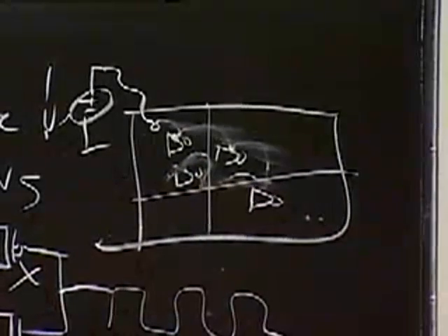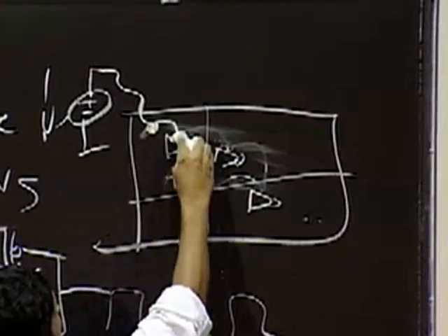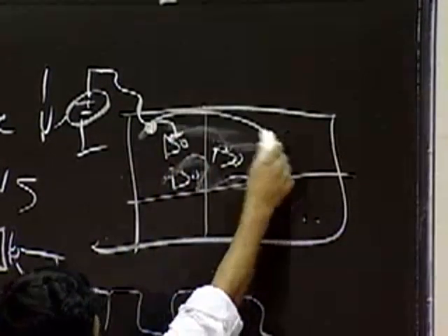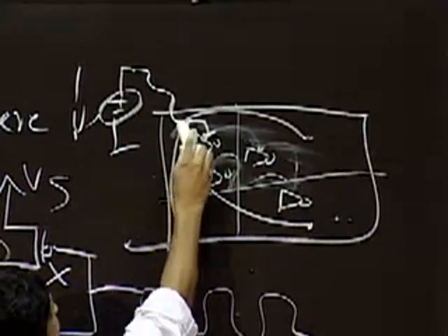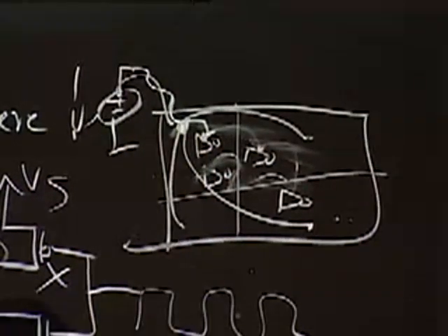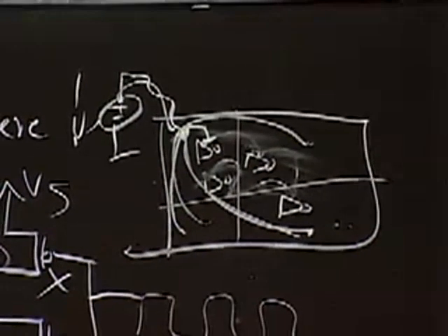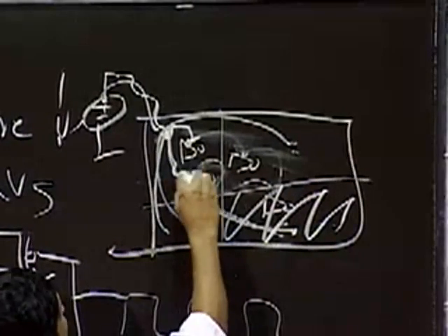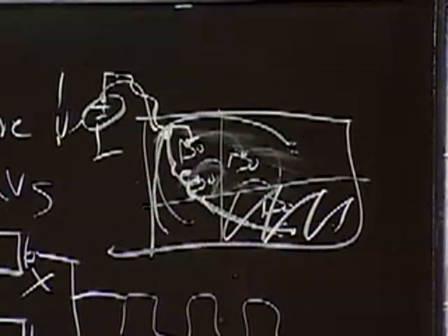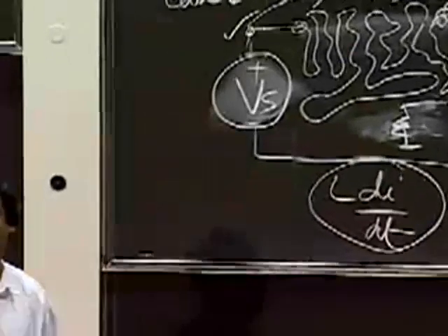In our case, we had 16 quadrants. And then from this point, you take one wire that goes to this quadrant, one wire that comes here, one here, and one here. That way you're getting the power supply very close to the source, and you have different connections going to each quadrant, so that switching in this quadrant does not affect this one because of the inductance of this lead here. And if you hadn't taken 002, you'd have been arguing with IBM, I don't want 16 wires, I want just one wire.